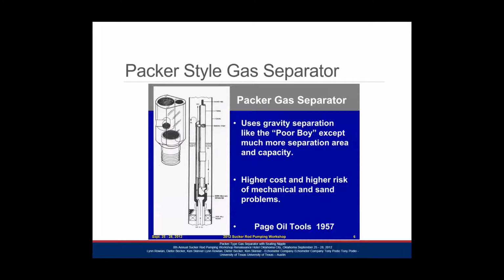Another type of gas separator is a packer style separator. It's something that's been around for quite a while, since the 1950s. We produce fluid, set a packer, and produce fluid through the tubing up an intake, and then the fluid will fall down. So we've created an artificial sump, just like the poor boy with gravity separation, and then gas will go up